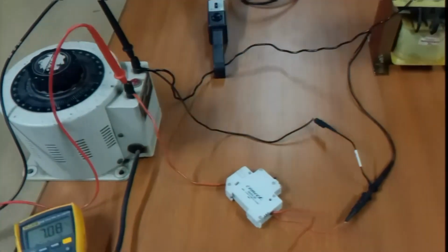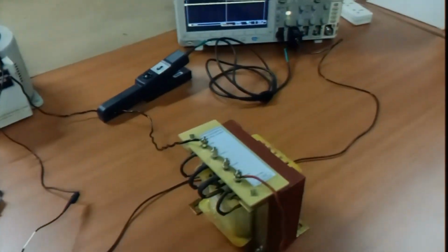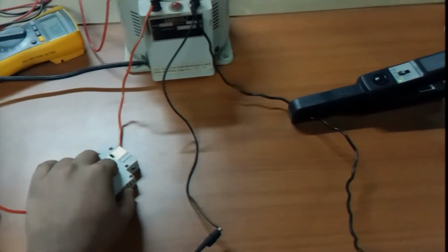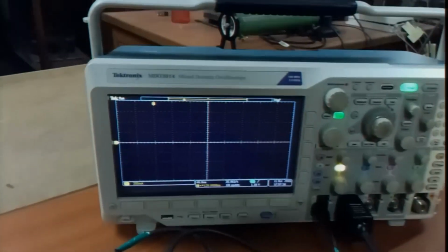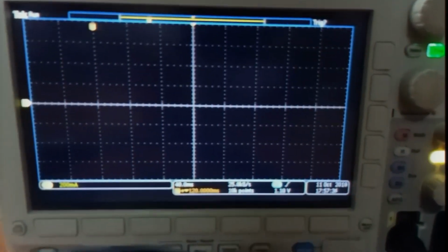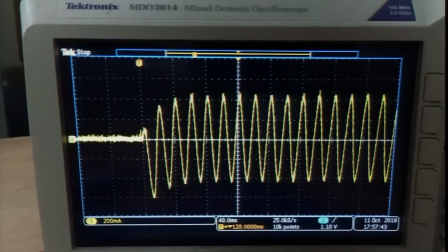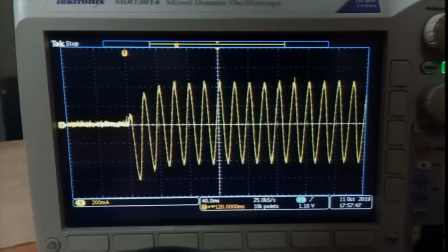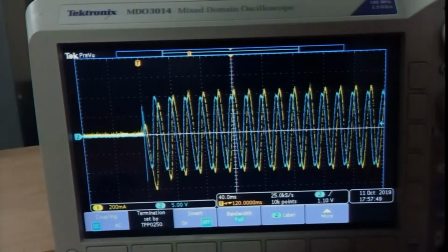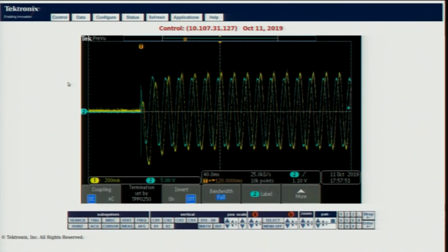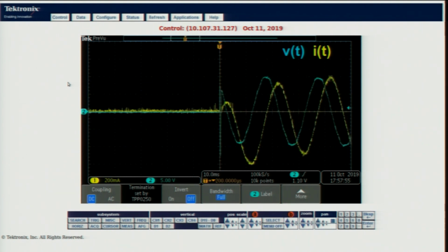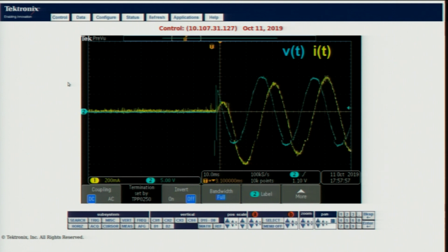So, this is 7 volts, but this is the RMS value. So, 7 into root 2 is approximately the peak voltage which you will get, and now he will switch this on. The instant at which this switch is switched on is almost random, because you are just switching it by hand, not really knowing exactly at what point on the sine wave you are.